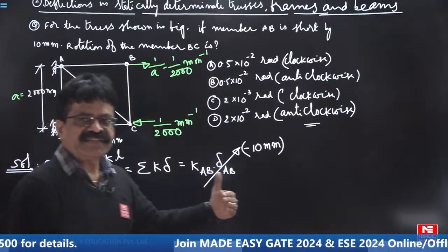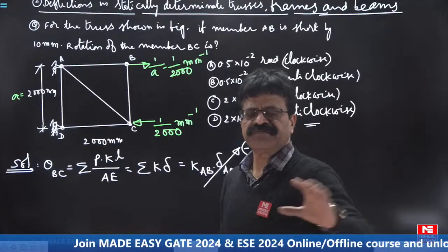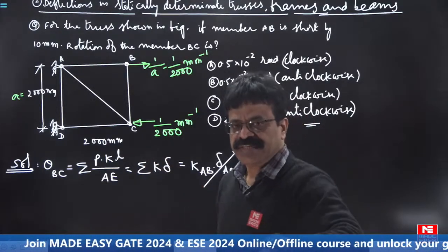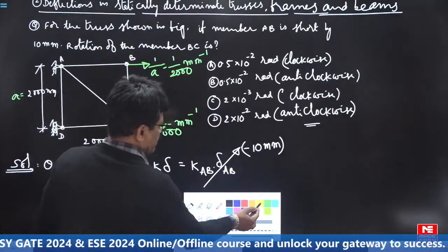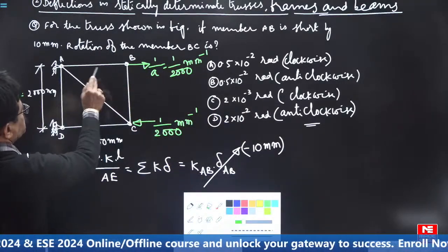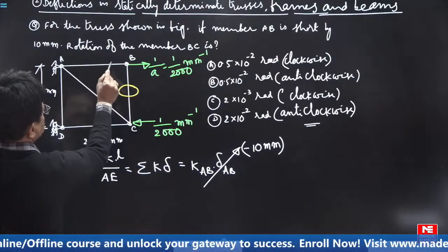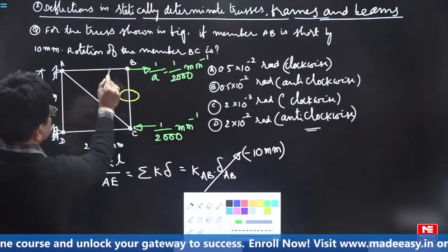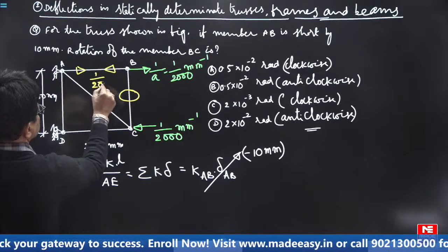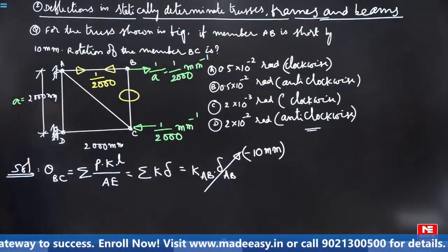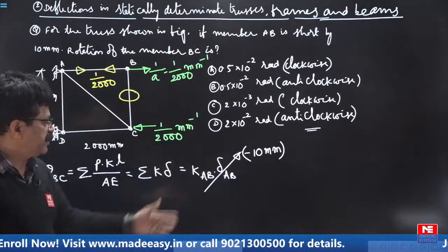The table and so on are not required. Whatever in the regular classwork we have written as tables and finding all the things, that is for the beginners. Now directly we are solving the problems. Now you see 1, 2, 3. 2 are in line, third must be 0. Right side, so it should be left side. Away from the joint, 1 by 2000. All other members you don't have to find because you require only KAB.